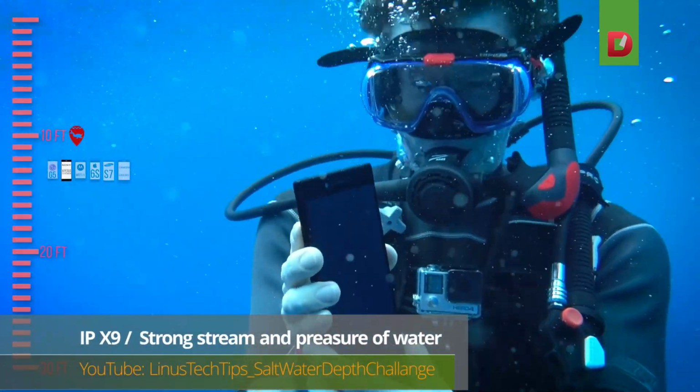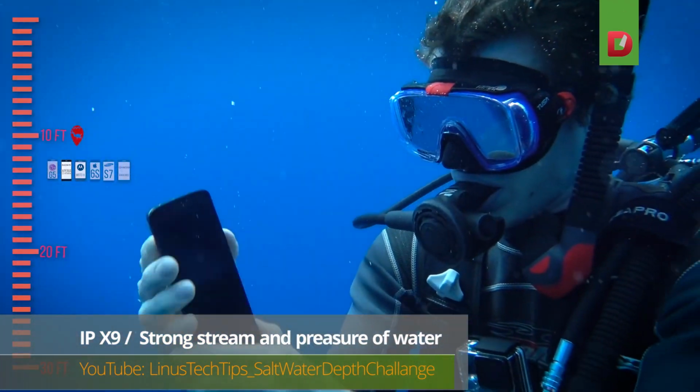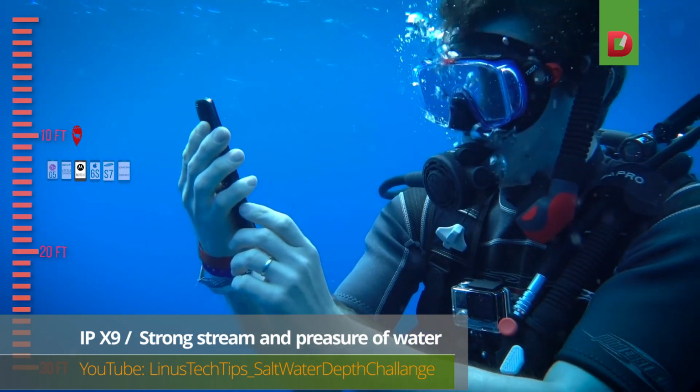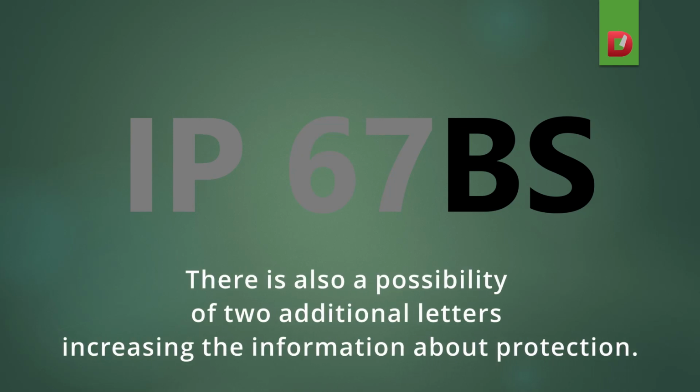Number 9 is protection against flooding with a strong stream of water, under pressure, from 80 to 100 bars, and temperature plus 80 degrees Celsius. Let us come back to 2 additional letters, increasing the information about protection.